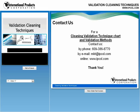All right. Well, let's see. Okay, here's a question. Is residue on evaporation applicable? I'm assuming they mean as a validation technique, and certainly that can be appropriate. Similar to TOC, though, you're not going to know what that residue is. So you won't necessarily know if it's a contaminant or a cleaner residue or if there's something in your water that shouldn't be there.